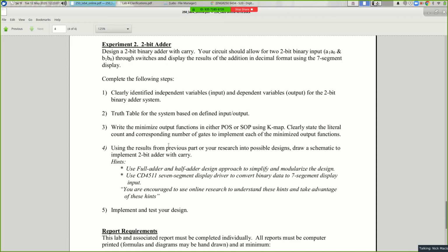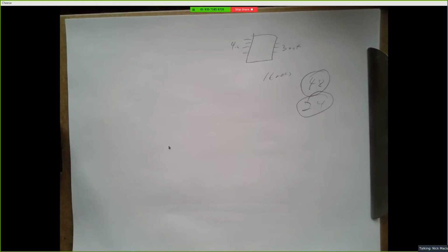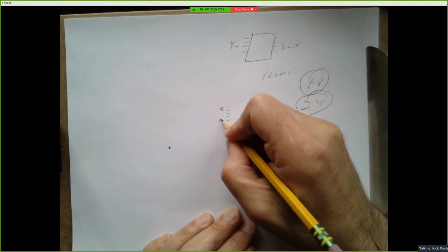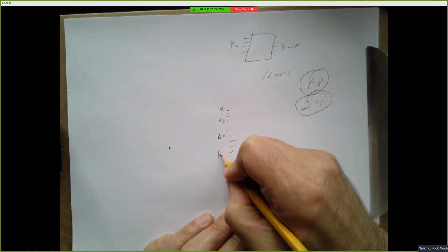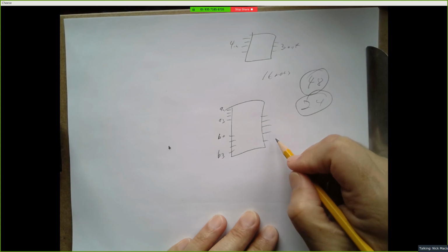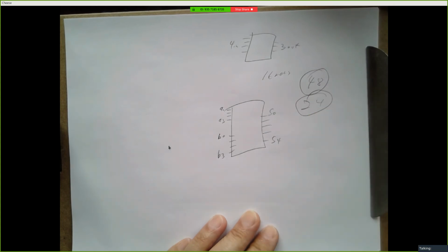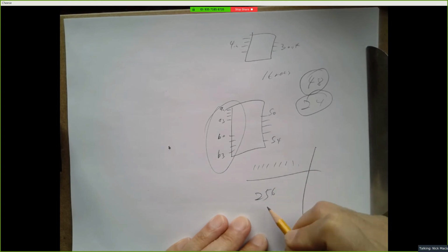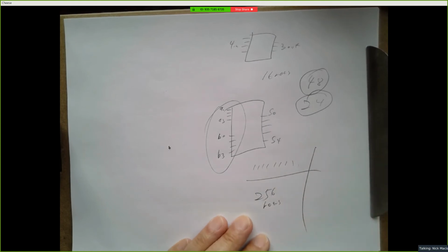It's 24 product terms you're going to have to create, 24 AND gates you're going to use, and then OR together in some combination. But suppose you wanted to make a 4-bit adder. So suppose you wanted to add A0 through A3 and B0 through B3 and produce a 5-bit sum. Well, you have 8 bits coming into this. That's going to be 256 rows worth of truth table.